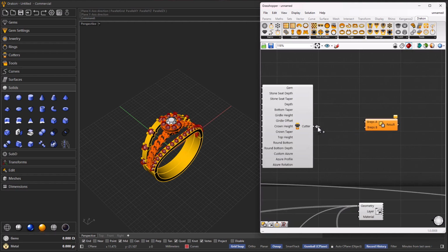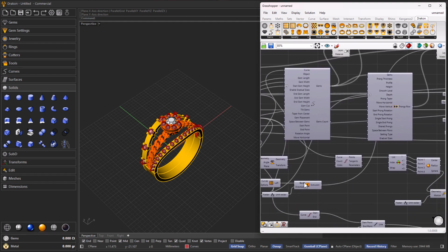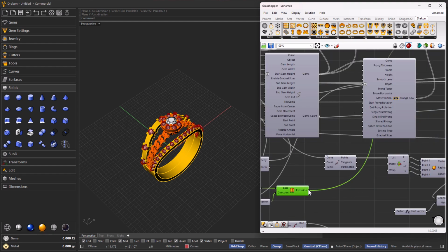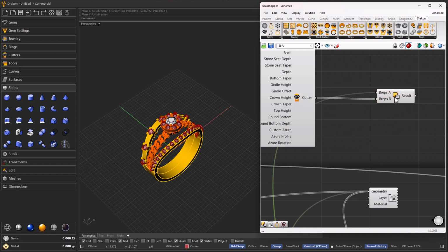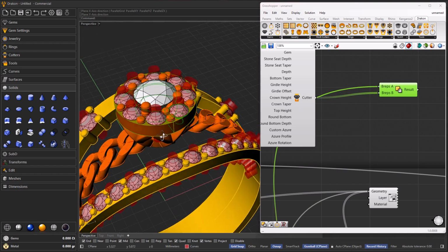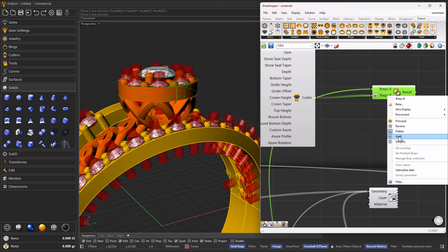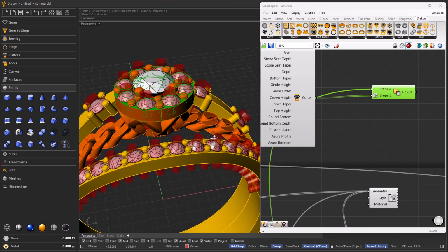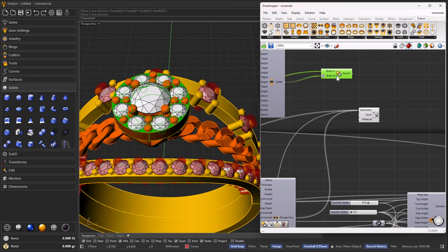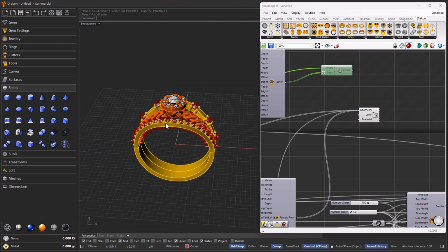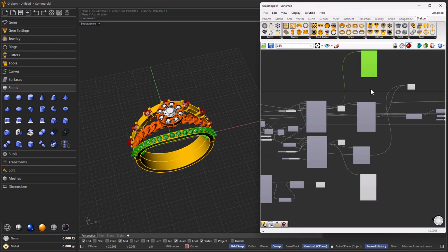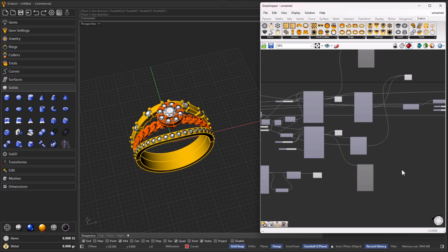So once again, we select the cutter as the object to remove and the object to keep. We would select either the extrusion, so we would make the Boolean operation here to make sure when it's multiple we can right click and graft the objects to make the Boolean operation. But this is just to show you the idea. Actually, I'm going to central mouse button and freeze the component just to not compute now, because this is the main idea, to show you how it works. Let me hide or freeze the cutters.